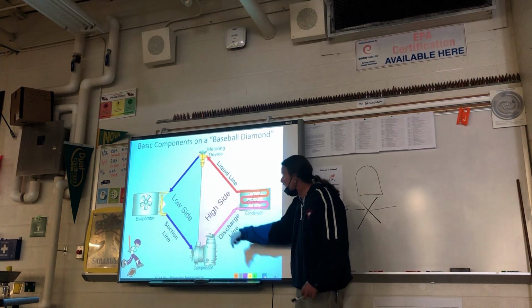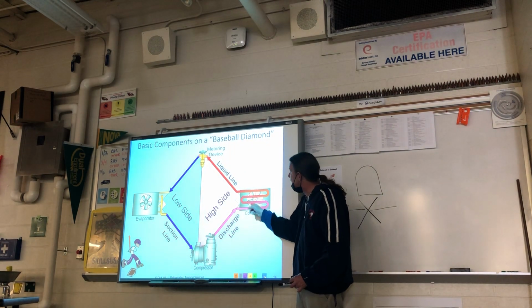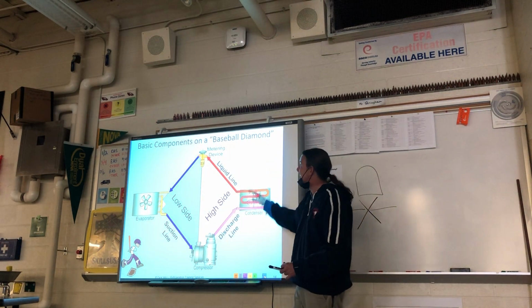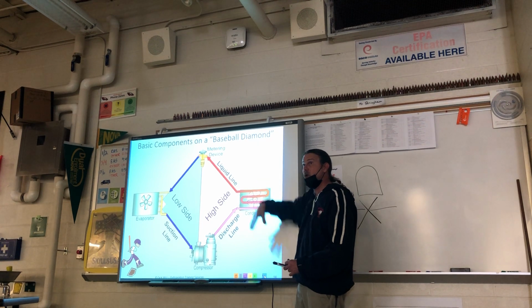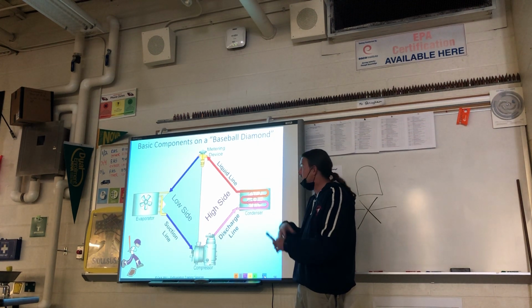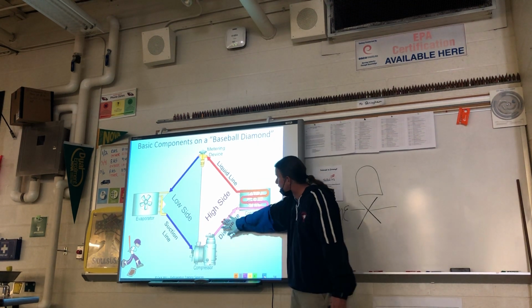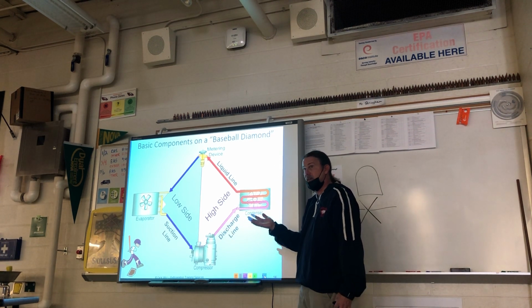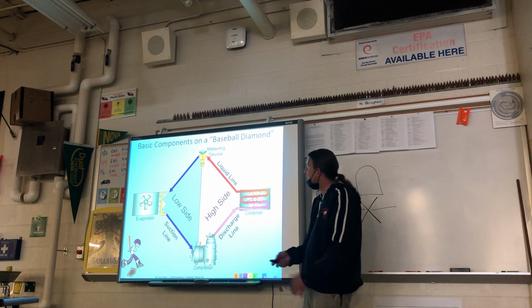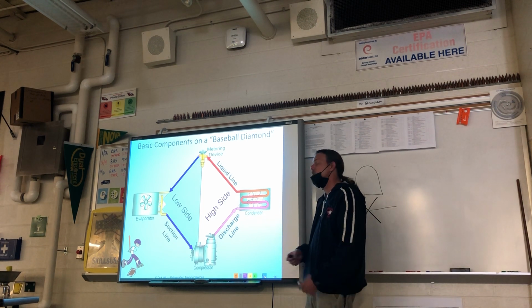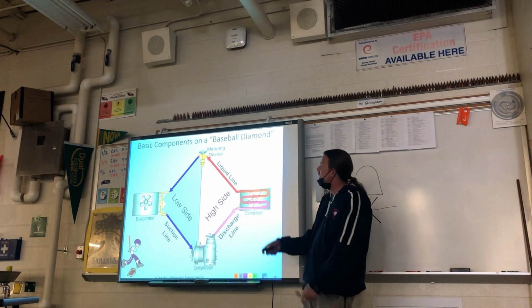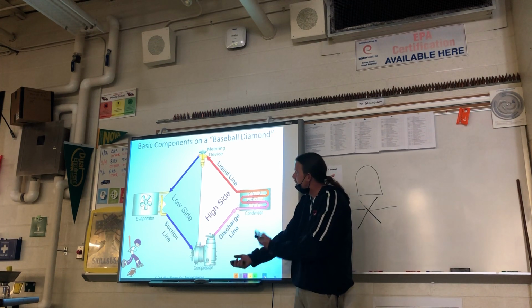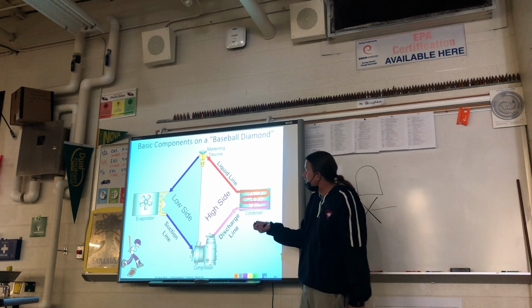At 300 degrees, if this fan motor stops running and this whole system's been running for a day like that with the condenser fan motor inoperable, and nobody caught it, and that's why you're out there, and you touch this line first off, you are going to have a third-degree burn. It'll give it to you. So you got to be very careful with this discharge line. You should be wearing gloves and long sleeves, all the right stuff. And most of our service shirts are long sleeve shirts, but you could be working for yourself one day.